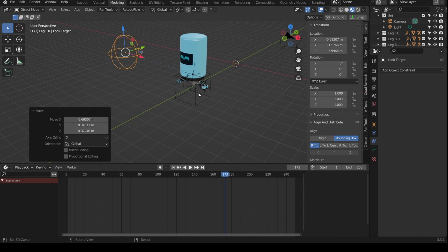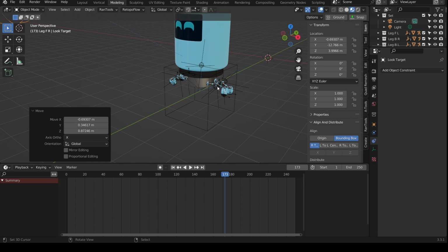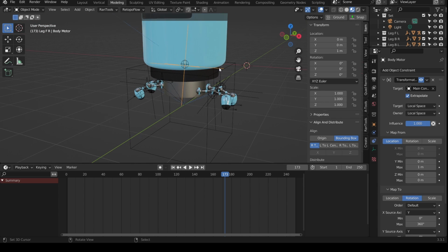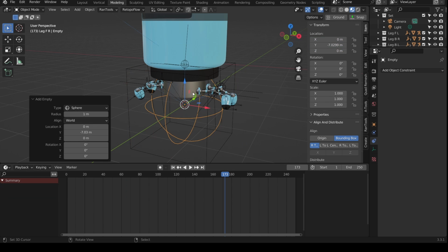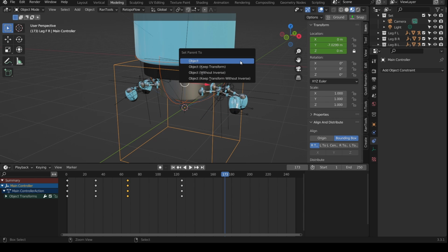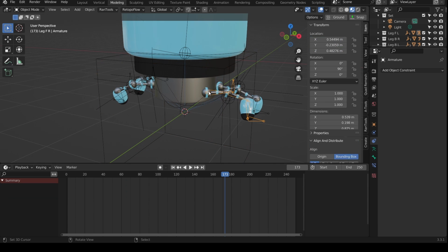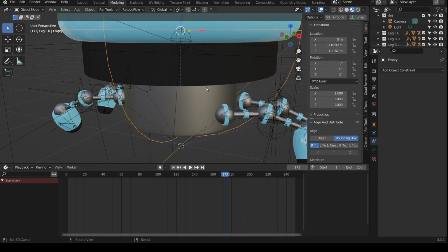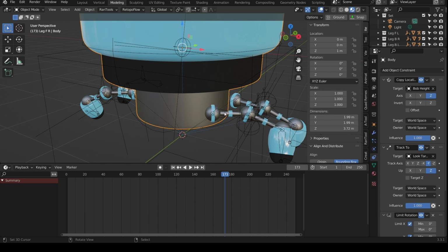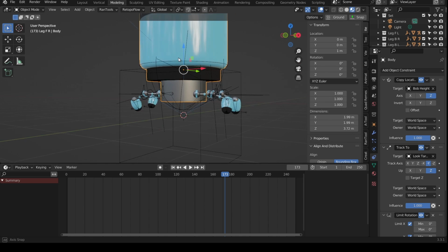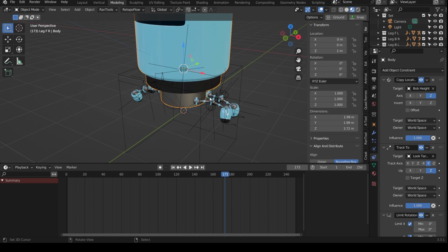You see? Now, if you don't like the legs moving with the body, you can actually change the parent. So for example, let's add another empty in there and bring it up here. Parent that to the main cube, and then instead of how we added the child of constraint, we can parent that to the empty instead. So instead of parenting these to this object, you'd parent them to this object, and then you'd parent the main body to the empty. That gives the extra level of freedom without affecting the transform of these objects.